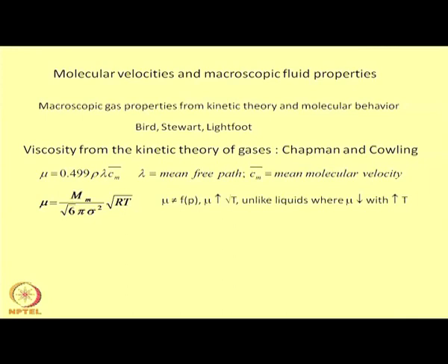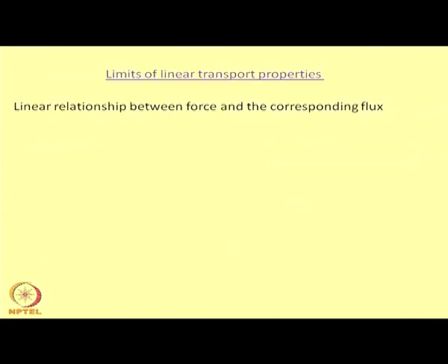From the corresponding equation, as you can see, mu increases with increase in temperature, and the dependence is root T, whereas in liquids we know that the viscosity decreases with increase in temperature, and similarly one can find relations based on kinetic theory from many of these textbooks for thermal conductivity and so on.